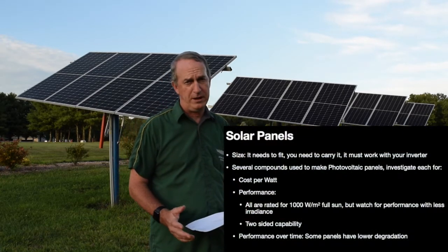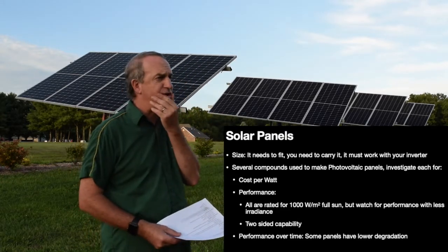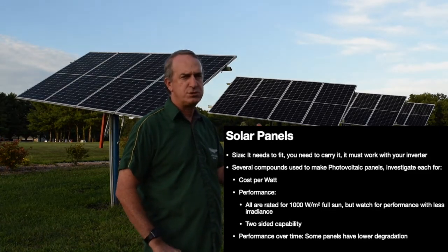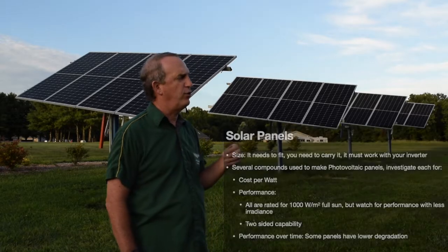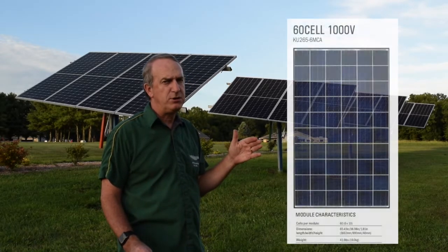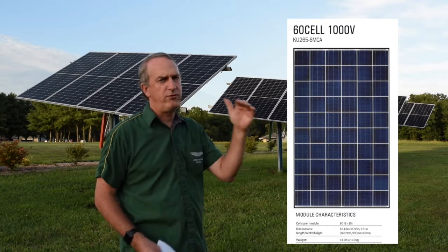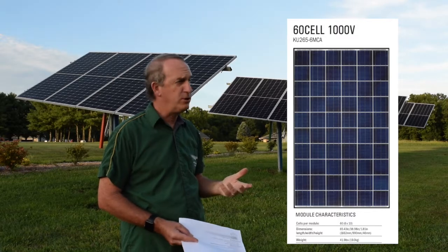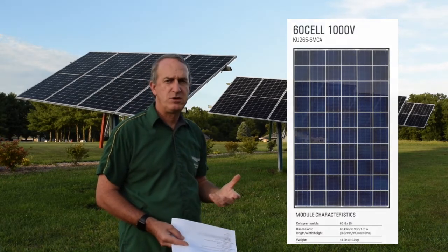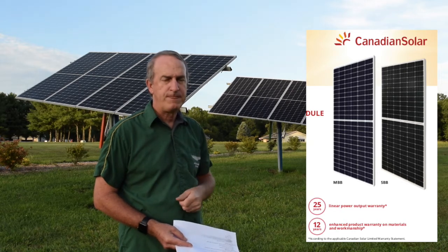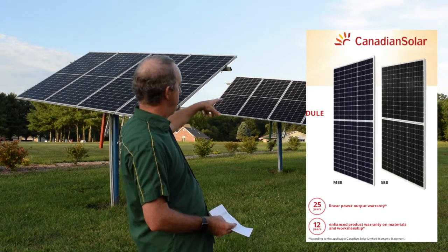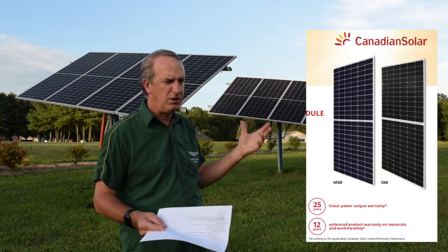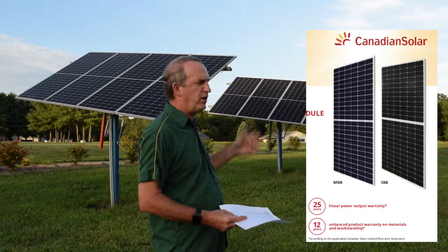So first off, you have solar panels, and I've got both sizes. There's 2 common sizes that are used for homes and businesses. They're both a meter wide, and one of them is 1.6 meters long and the other one's 2 meters long. The 1.6 meter panel is 40 pounds, so it's relatively easy to pick up and hoist to the roof, whereas the 2 meter panels that you see here are 50 pounds apiece, and they're a little bit ungainly, but they have some advantages as well.